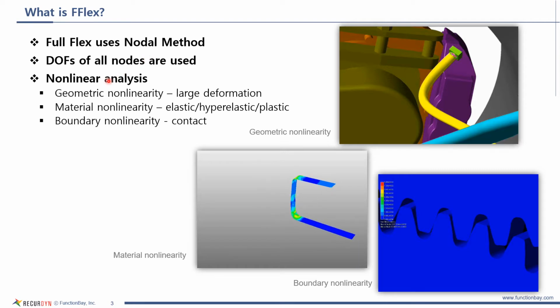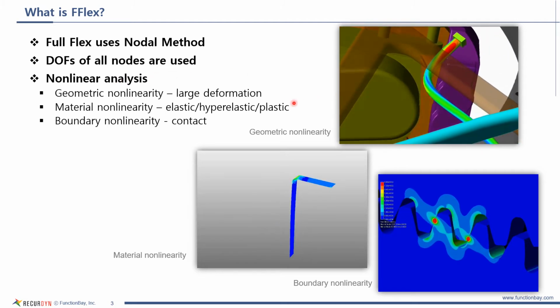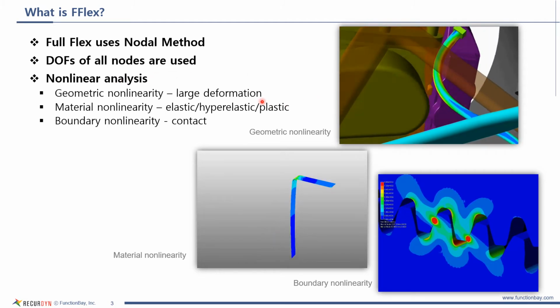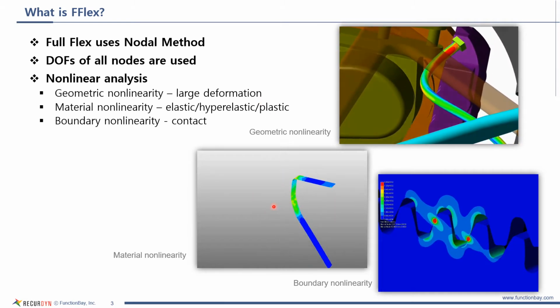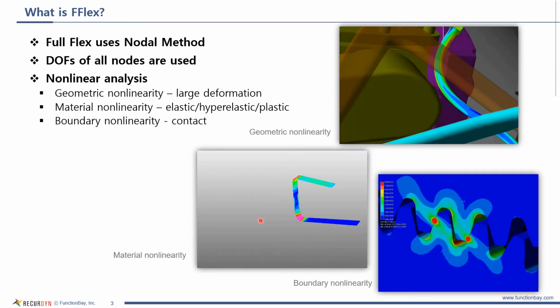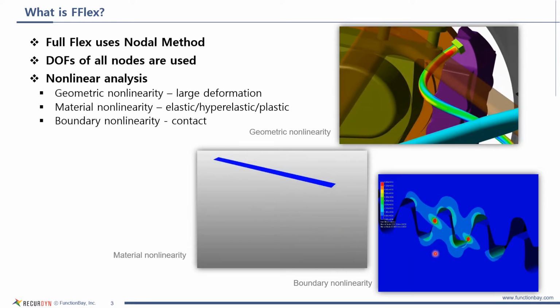FFlex supports geometric nonlinear problems such as large deformation problems, and it also supports not only linear elastic materials but also material nonlinearities such as hyperelastic and plastic materials. Boundary nonlinearities like contact are also supported.